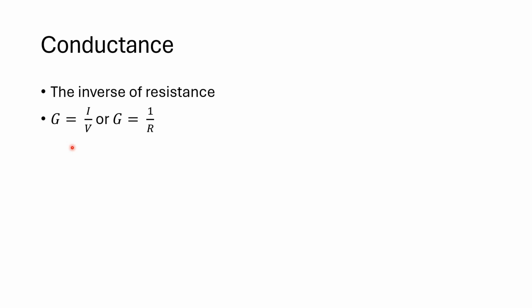And then from there, you can calculate the resistance of the wire. So if you want to in lab, we can do a little bit of measurement. We can figure out approximately the resistance of that wire for a given length. Conductance is normally given in terms of length because as you add more wire, you have more physical stuff for those charge carriers to get through. And the more stuff you have to get through, the more you're going to be limited because you're always going to have a little bit of resistance in life.